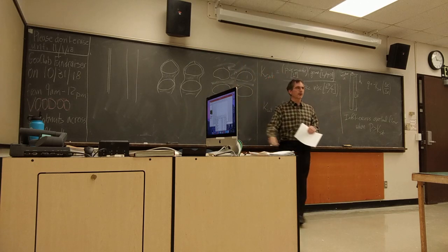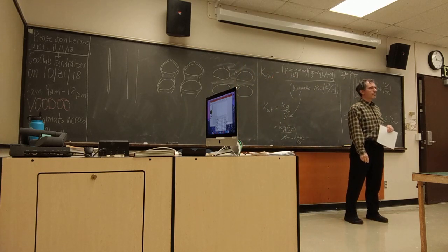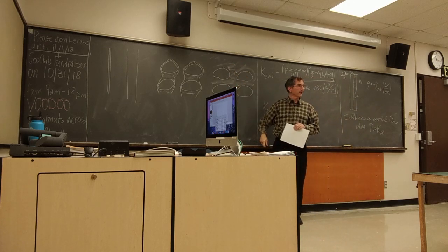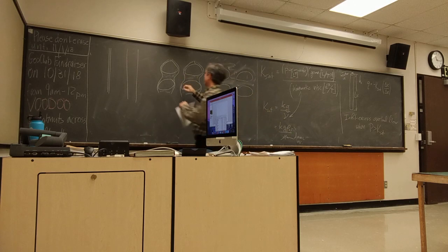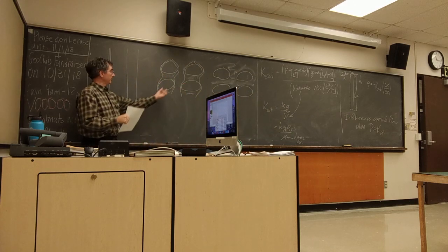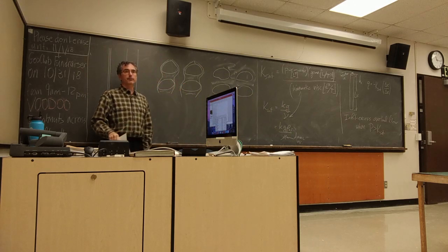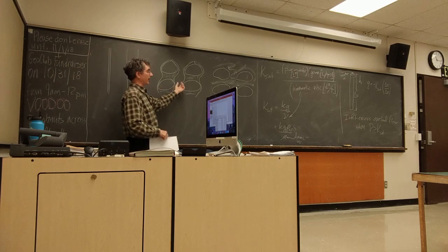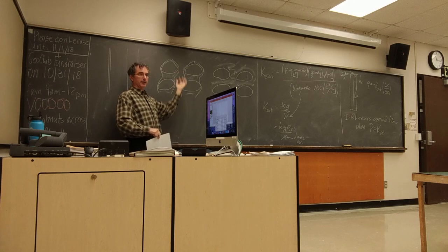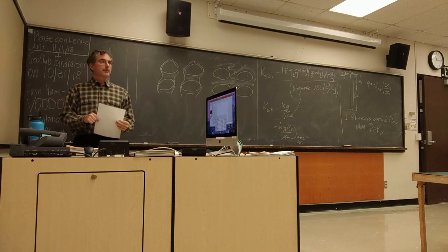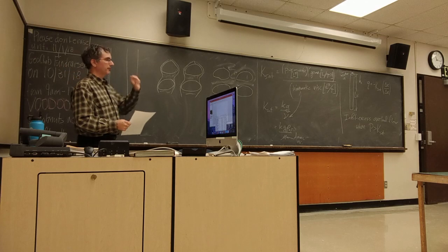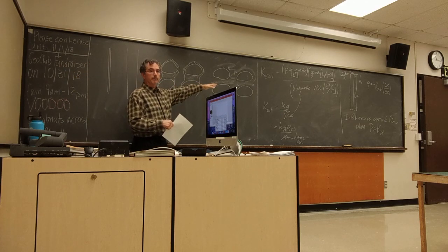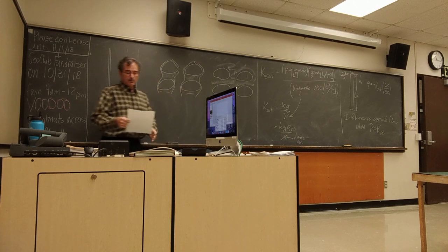in which case does the water have the bigger tube? Right? Here it's got the whole pore space to flow through. Here it's only got the thin part, it pinches out. It's got to flow through those thin spots. Now, it's somewhat aided by the fact that the water is held in tension, that it's going to tend to pull the water in a bit. But in terms of our hydraulic conductivity, it's the maximum when it's saturated. Okay.